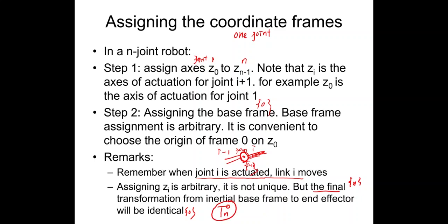So again, for the forward kinematics, we care about the final T_N^0 because this means my end effector orientation and position in the frame 0, which means in the world coordinates. And this is what we really want to see because, for example, if we want to control the robotic arm in manufacturing in whatever tasks, we actually need to know at each time point, at each world space location, what the tooling is.